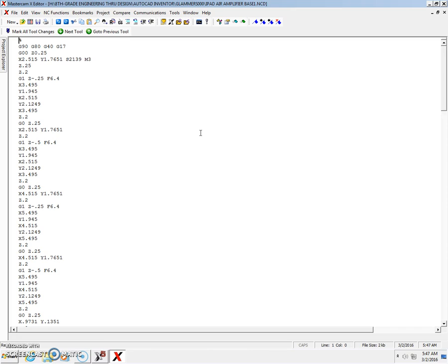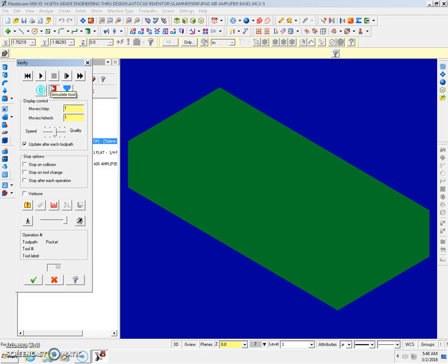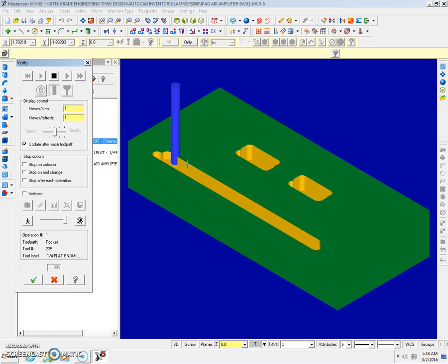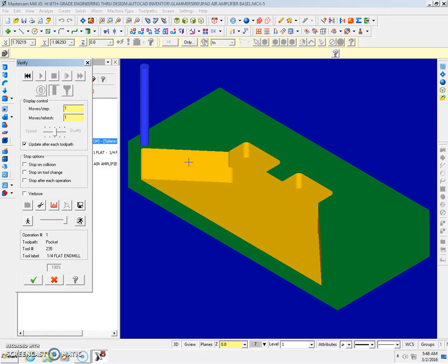Once you click the green check mark, the Mastercam X editor file is going to show up. For your viewing, we're just going to X out in the top right hand corner. Next, we want to verify our selected operations. That's this tool right here, Verify Selected Operations, right next to G1. Once your screen looks like this, we're going to click the play button. And you want to call Mr. Lammers or Mr. Bowen over at this time in order to view what your part looks like. Green check mark.